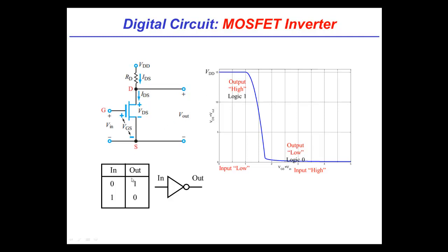Okay, now let's look at the other case. Let's say I put in a really big Vin. What's a really big Vin? Well, the digital circuit before this could really only put out VDD as its biggest value. So let's say we put in VDD here. Well, now we know VGS is going to be very large. Right. So what do we know about the equivalent through here? Well, if VGS is going to be large, that transistor operates like a voltage-controlled current source and will pull a lot of current. That's right.